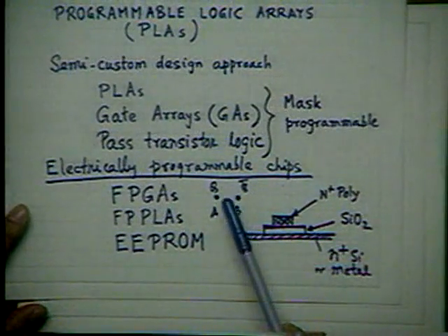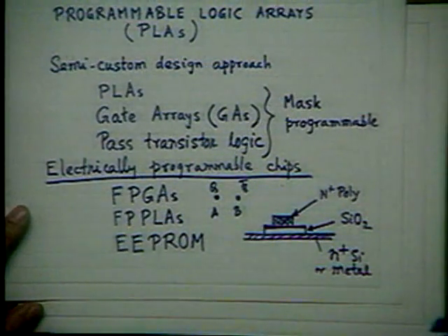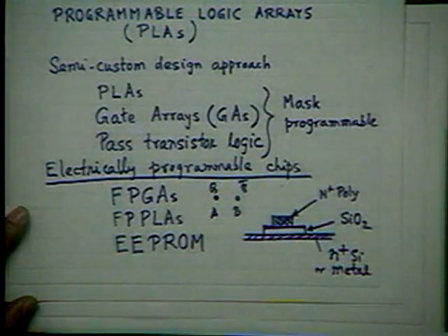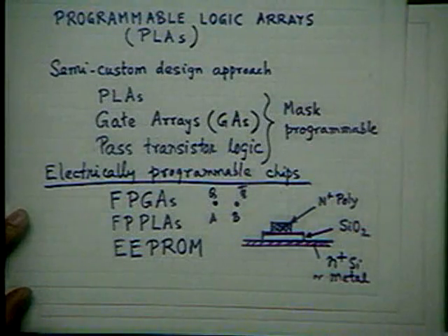This can be done by making use of a normal RAM with a battery backup. So in that case, it is very inexpensive. RAM with a battery backup is practically equivalent to a ROM. You can program it and keep it, so long as the battery life is okay. So if you use RAM with a battery backup, then you know the RAM can be formed in a relatively high density. High density means not as compared to dynamic RAM.